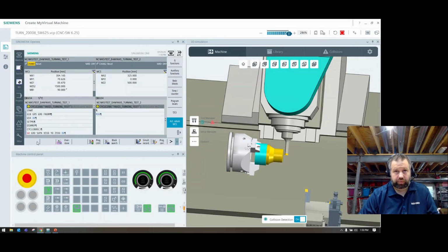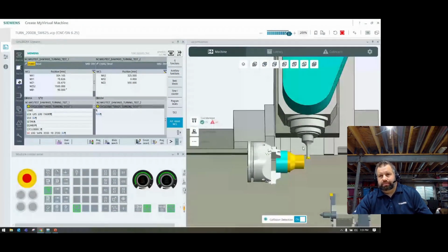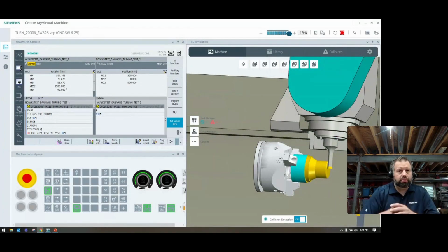All right, keep going, Dan. Sorry, I'm going to look to see if I missed any. To that point, Chris, one of the things that's nice about our control is that, as long as you're using our spindle drive, the spindle can be turned into an axis. So you can just dictate 0, and now it's 0. And you can change that. So in that speeder application, you just say S pause equals 0, and now it's 0. That's super huge.